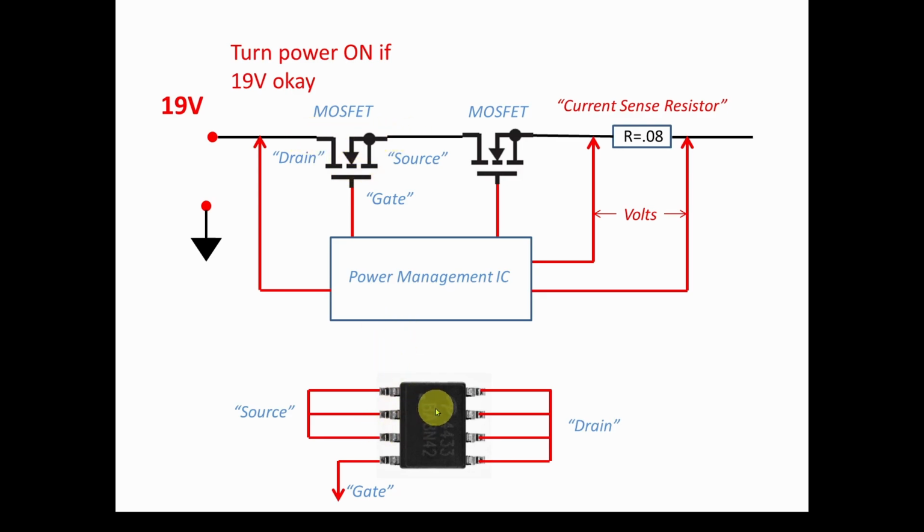You can get more current, so you have parallel circuits tied together. If you can have 1 amp in one, 1 amp in the parallel one, 1 amp in the other parallel one, that allows you to carry 3 amps rather than just 1, so it gives you more current carrying capability. The gate doesn't need that because it's just a control signal, very low requirements.